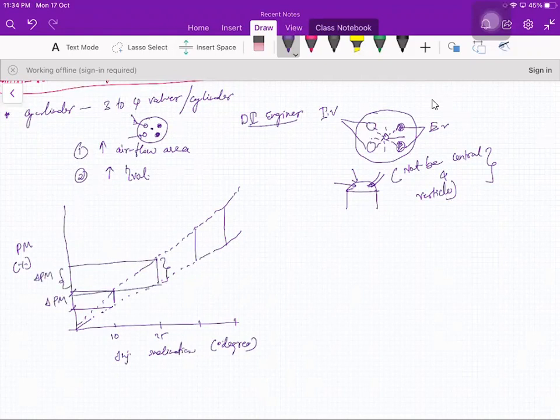Likewise, the more degrees deviated, the more particulate matter emission will be increased. This is due only to the poor fuel distribution in the cylinder because of its orientation.